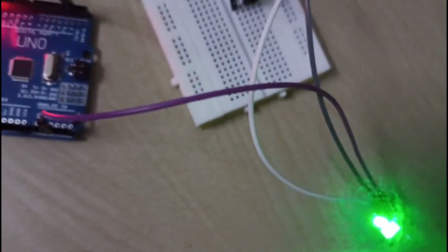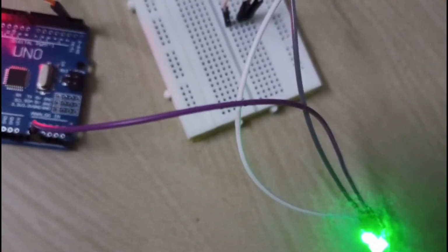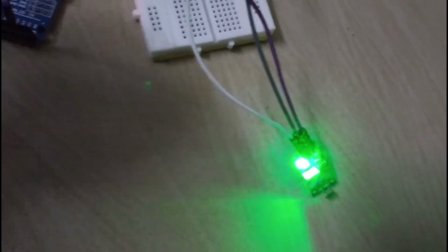Now you can see the serial monitor values. Yes, the LDR value is 1000. But as per our program, we need to consider it only if it is less than 500. You can see more lighting is there. That's why the reading is 1000. Though my IR sensor is able to detect the motion, there is no change in the LED.